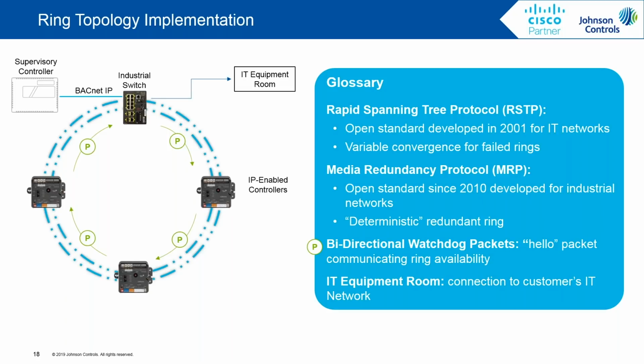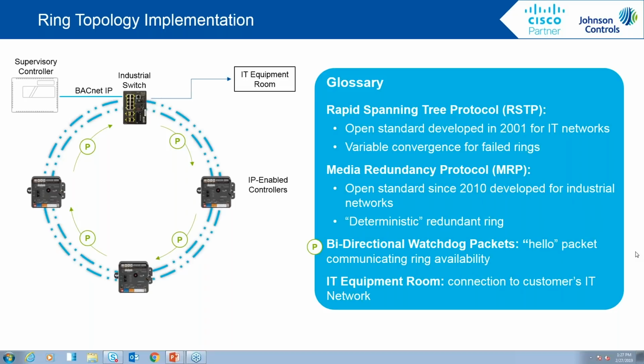Because of that, it has a very deterministic ring convergence time, which means it's centrally controlled, based in hardware, to control who has the master of the ring and the timing involved in it. Again, very deterministic, very fast.